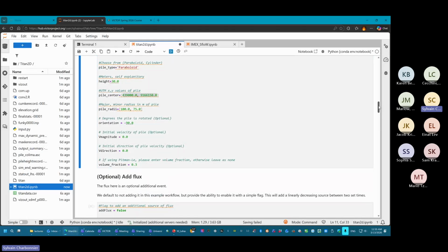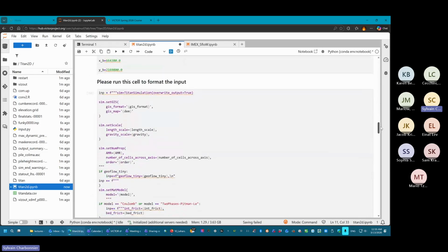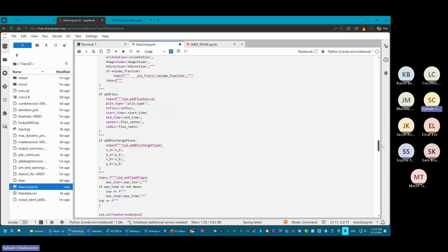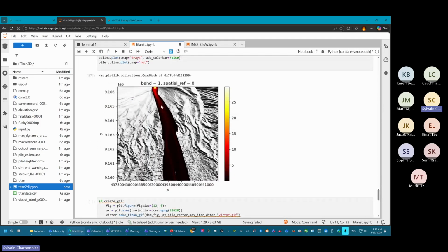You will see, because the slopes are very, very steep at Merapi volcano, and so I can show you what I was getting in the end. I was getting a lahar that is going out of my DEM boundary, and I was getting velocities of about 50 meters per second in this location here, which is way too high for a lahar, and that's because I forgot to change the location of the initial pile, right?